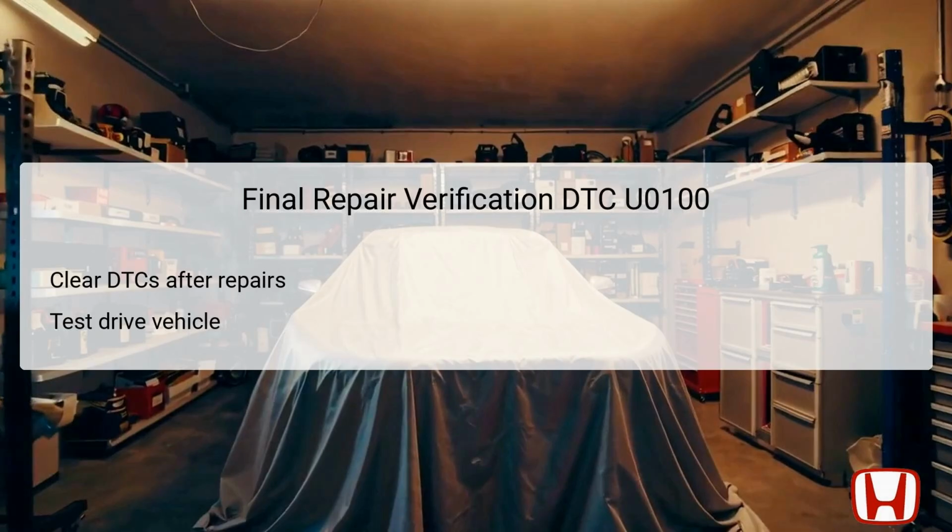During the test drive, technicians should observe if any DTCs reappear. If the vehicle operates smoothly without triggering the DTC again, it confirms that the issue has been successfully resolved. A careful approach to this verification step ensures that the initial faults have been addressed effectively, and that the BCM and ECM PCM communication is restored.